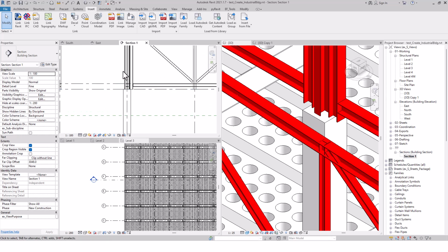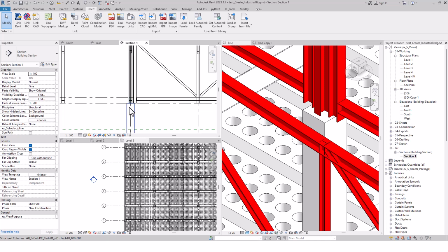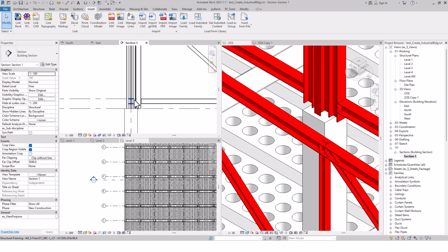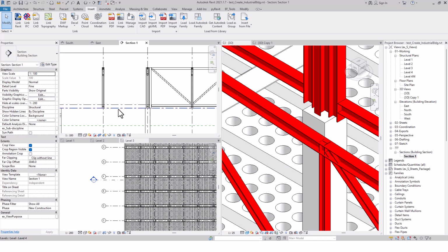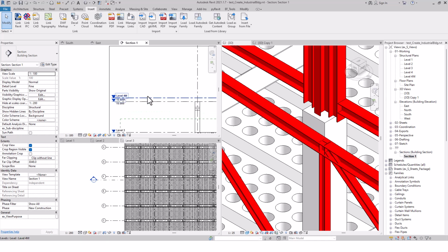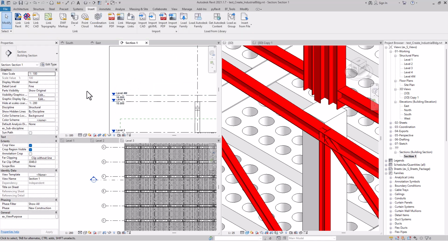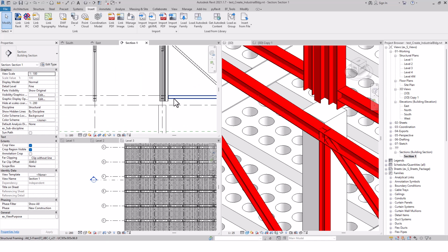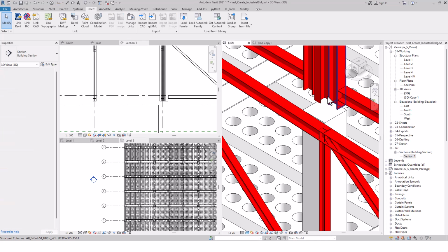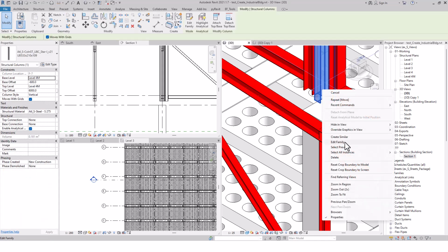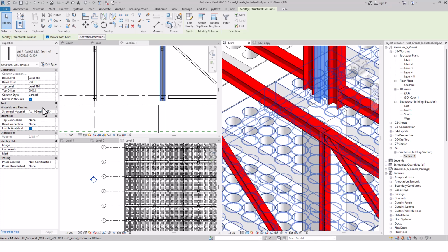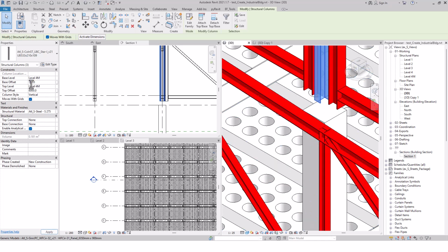What's going to happen is that this main column will be sitting on top of the concrete column, and they will have a corbel there. So this height should be more than 600. Make sure that this one is brought up by another, maybe 400 for example. Then all the columns will be going up, right? So at this time we have to select this steel column, right click and select all of it in this view, and instead of -600 it has to be 1000,